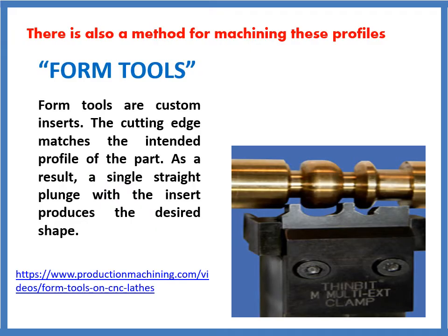But there is also a method for machining such profiles, and the answer for such profiles is form tools. And what are these form tools? These are customized inserts, and the cutting edge matches the intended profile of the part. As a result, a single straight plunge with the insert produces the desired shape.